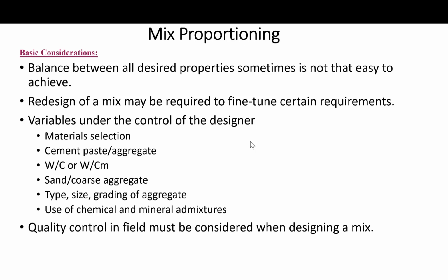The durability requirements the same way, but you have many things that you can control in order to manipulate these variables and come up with a mix that meets the specifications. Also, one thing to consider, as I mentioned, the quality control in the field must be considered when designing a mix, because you have to factor in the less than perfect practices.